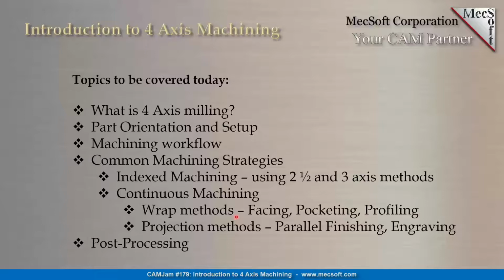And then we'll also talk about projection methods, where we're talking about parallel finishing and engraving. We'll do this in the introductory. There are other methods that we'll go into in the next webinar, but we'll start out with the parallel finishing and engraving for this webinar. And then finally, we'll show you how to post-process these toolpaths.